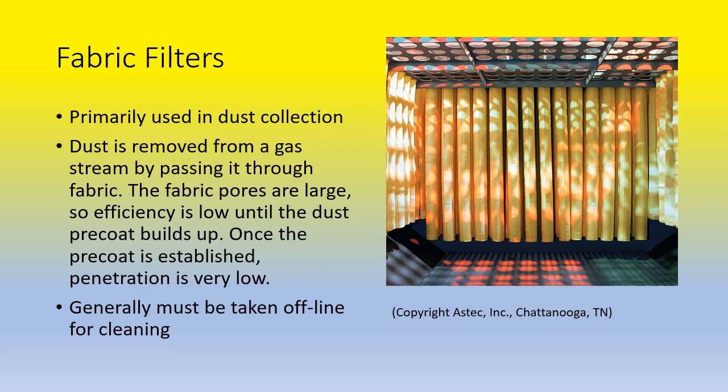Fabric filters are primarily used in dust collection. So how they work is that dust is removed from a gas stream by passing it through the fabric. So they are fairly simple, probably one of the simplest filters besides a coffee filter. So the fabric pores are very large. Efficiency is low until the dust precoat builds up.